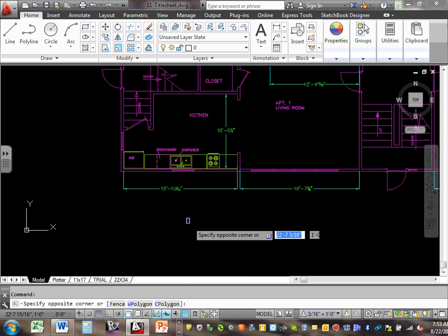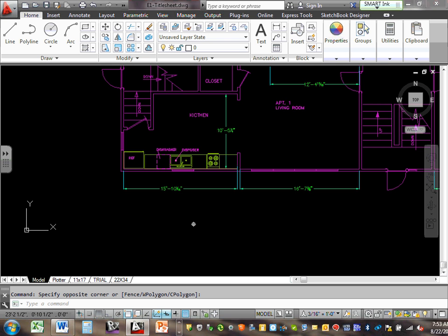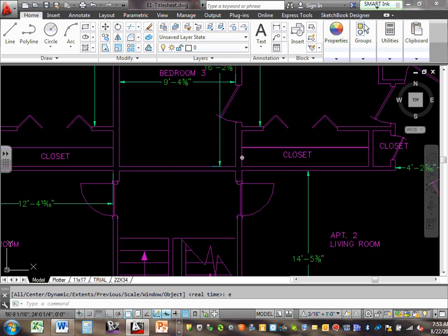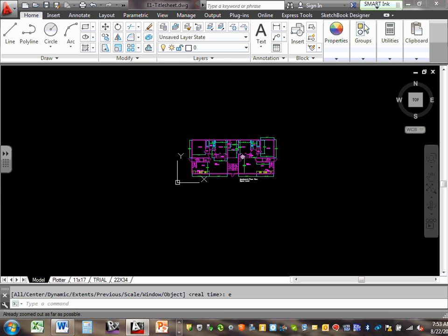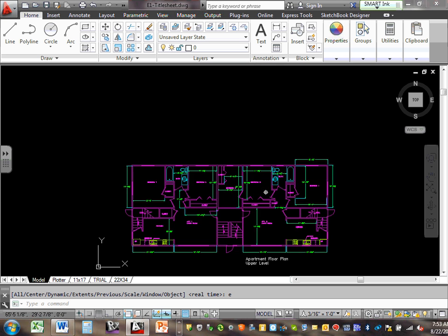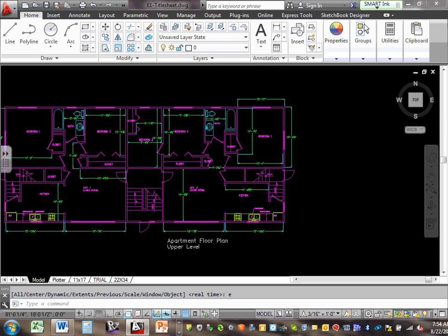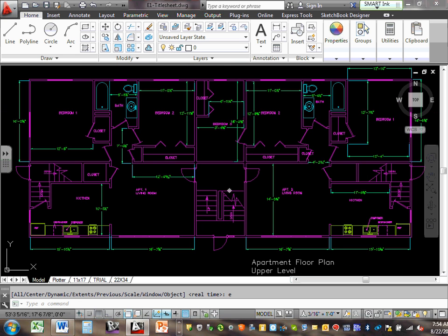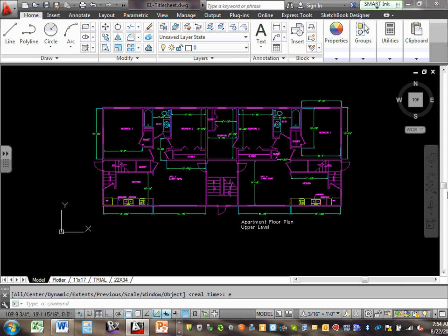Okay. Now I know you guys have 3 days of experience with AutoCAD fundamentals. Now we're going to use them. So do me a favor. We're going to go Z enter E enter. So hit Z enter E enter. It will zoom and make you look at the whole project. So can you see now, if you have the wheel, we said we're going to have a mouse with the wheel. Can you guys see how I can zoom with my wheel onto the apartment? If you are here, like here, one more time, Z enter, E enter, will get you to see the whole apartment.